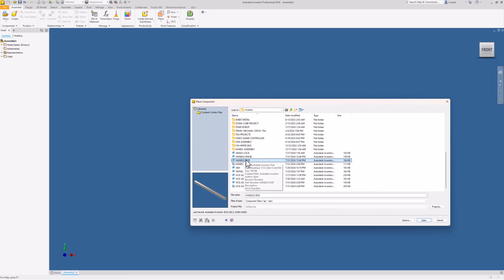So I'm going to go up to Constrain. I'm going to use the Insert option. I want to rotate this to where I can look inside. That didn't really work out. There we go, like so. I'm going to click this back circle, this back circle here, and it clonks that in. I'm going to hit apply. I'm going to do the same thing here. I'm going to click this back circle, and click this front circle this time. Hit apply.